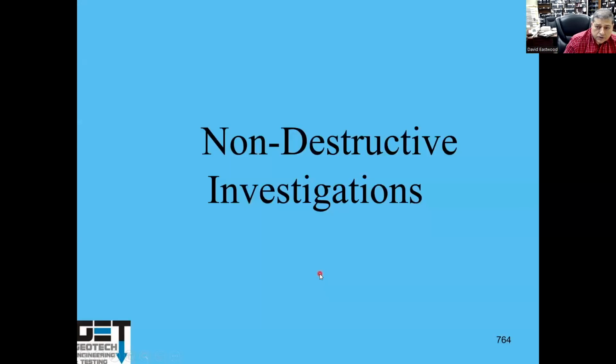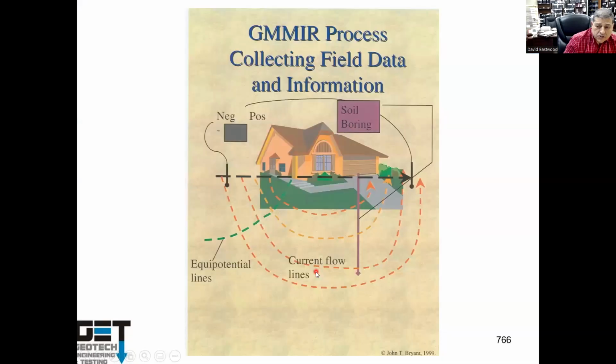You can also do non-destructive testing. Resistivity. When we do soil testing, it's a one-dimensional deal. If you want to know three-dimensional what's going on underneath your slab, you can do what's called resistivity systems. You put probes in the ground, run electricity on it.